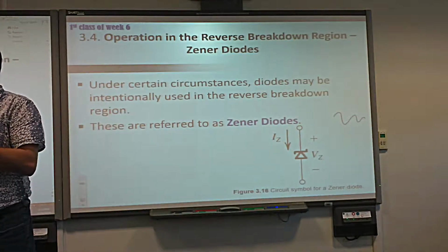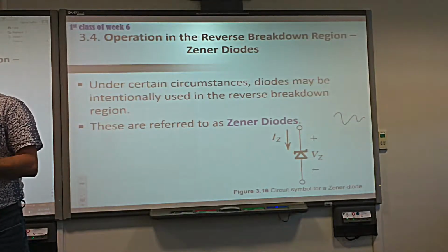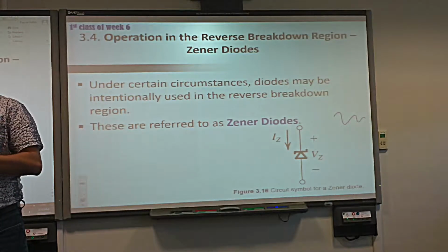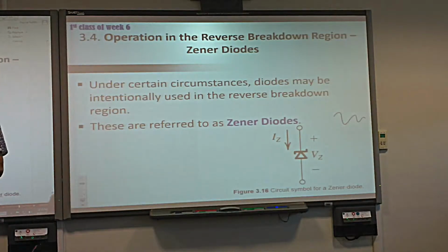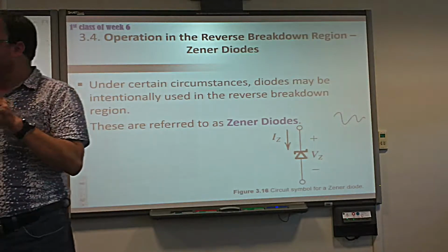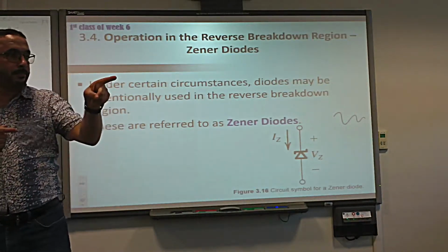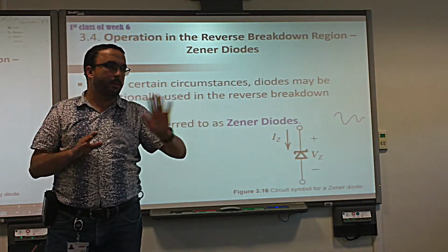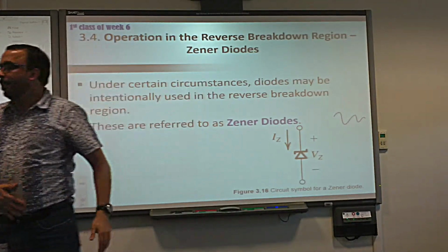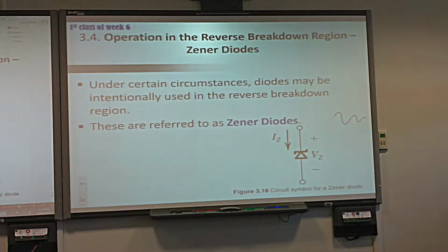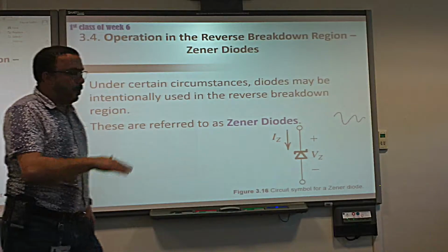A small signal model is only for AC analysis. Okay, small signal analysis of the diode. It's a model specifically for small signal analysis. If we are doing DC signal analysis, we have 3 models: exponential, CVD, and ideal. But all of them are forward bias. All are forward. Now we are talking only about forward. Good question. So these 3 models are only for DC analysis, and I have shown you that. So that's for the forward bias.